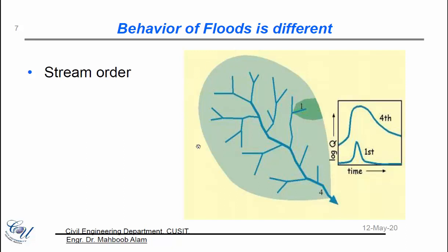You can see here that we have a certain catchment and we have a river which is flowing in this direction, and then there are certain streams which are meeting this main river and draining its water into this main river, which is ultimately going out of this catchment area. Now this, for example, stream order is important to look into because if you are somewhere here in this area, then the design that you are going to do for flood control structures should be different than the designs that you are going to employ in this area. And it is understandable because this is the area which is kind of head catchment, and the discharge here would be less as compared to discharge here, because here we see that all the streams are ultimately combining here. So it's important to understand which stream I'm working on.